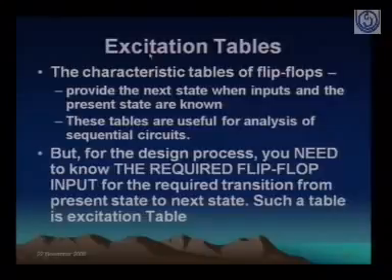Okay, now one more thing we want to define about the flip-flop, and that is called excitation tables. You must be wondering, we talked about the characteristic table, right? What do the characteristic tables of flip-flops do? They provide the next state information. So what will happen if the inputs S and R go to this particular state? But they are not particularly useful for design. These tables are useful for analysis of sequential circuits, but not for design, right?